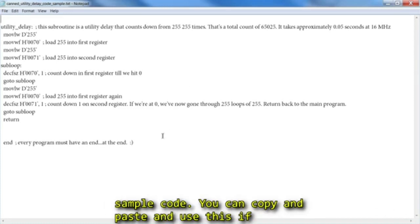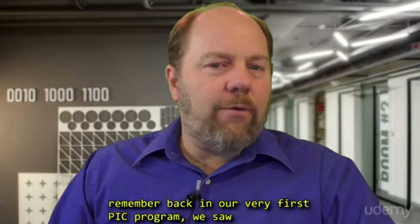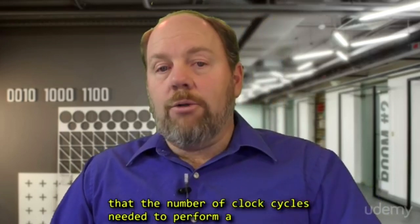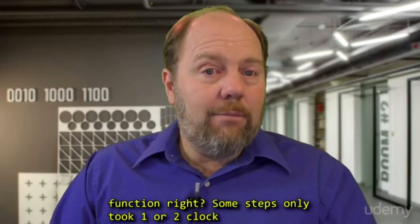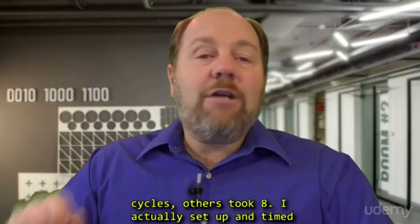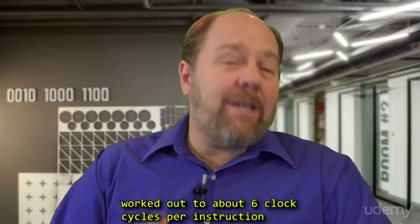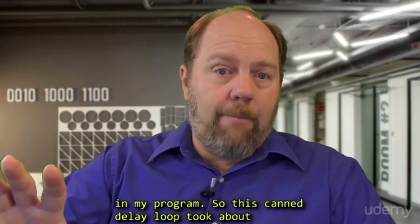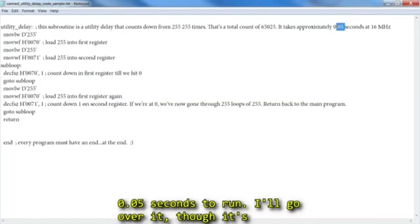in the sample code. You can copy and paste and use this if you want, and I already figured out the timing. So you remember back in our very first PIC program, we saw that the number of clock cycles needed to perform a function can radically change from function to function, right? Some steps only took 1 or 2 clock cycles, others took 8. I actually set up and timed the program to get a handle on timing, and it worked out to about 6 clock cycles per instruction in my program. So this canned delay loop took about 0.05 seconds to run.